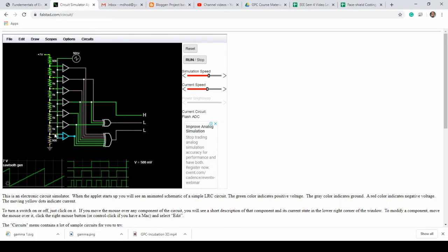Now each operational amplifier would detect this rise in voltage and would turn on, and with this turn-on pattern, through these XOR gates, it will give you an output of 0 if the voltage is 0, and then the pattern of 1s and 0s follows as the voltage rises.